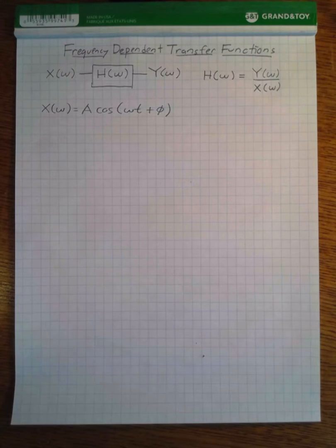And that's what Fourier analysis is all about, showing how you can construct an audio signal or a wireless communication signal from a sum of sinusoids. And so when we analyze our frequency-dependent transfer functions for a single value of omega, the same transfer function can be used for input signals that are made up of a summation of many different sinusoids. So this is a very general purpose analysis that we're going to be talking about.